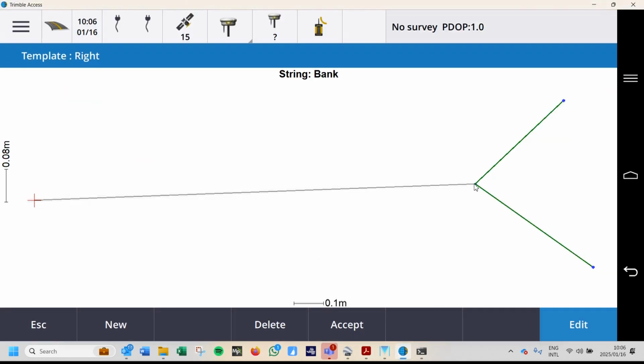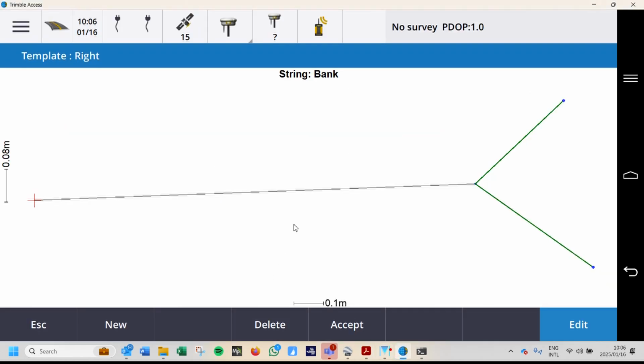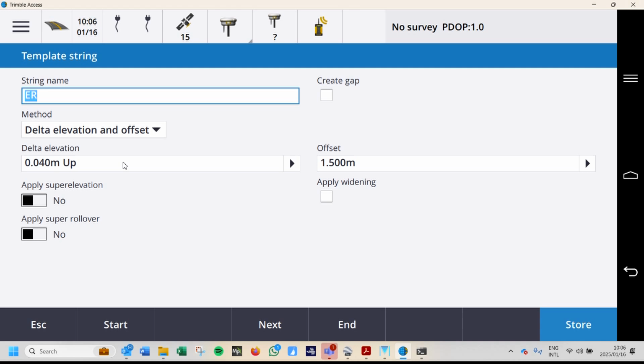So we have to change our point there, our offset has to change from +4 to -3 in this case. So to do that, we're going to select that road entity, make sure that it is highlighted, and then go edit.